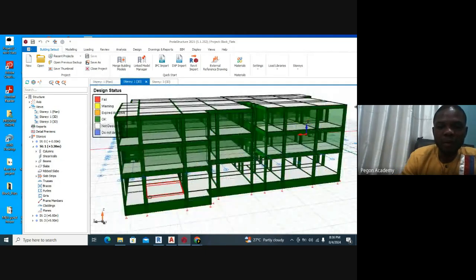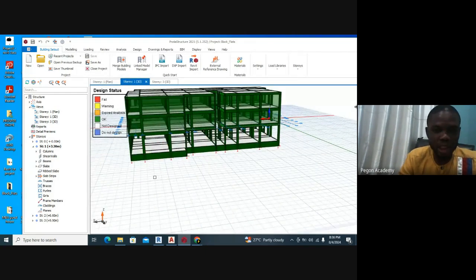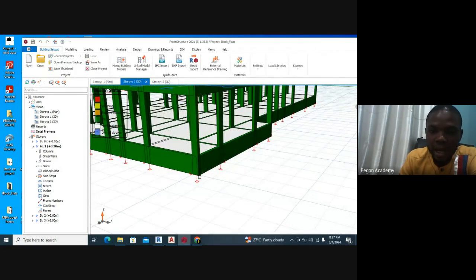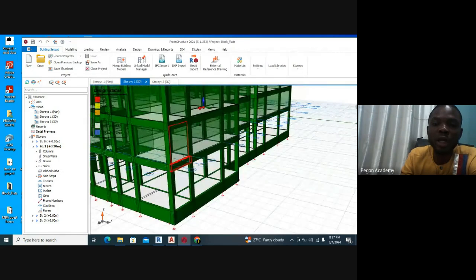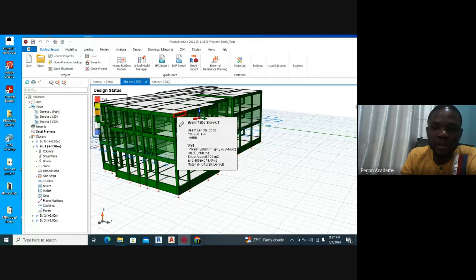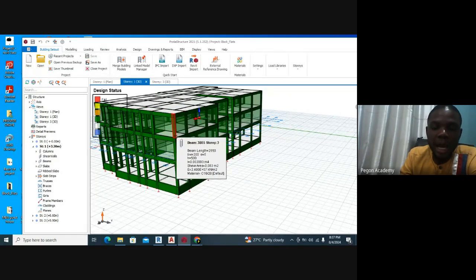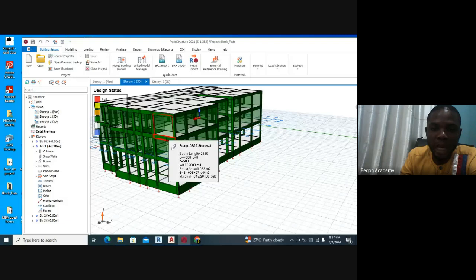Now, a normal pad foundation has the footings below each column, right? You must know what I'm talking about if you are into construction. Maybe 1 meter by 1 meter by 300 mm below each of the columns. So the loads come all the way from the roof down to the roof beams, down to the columns, and then down to the other beams here.